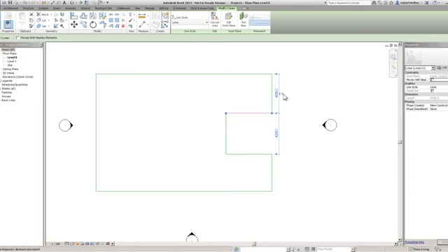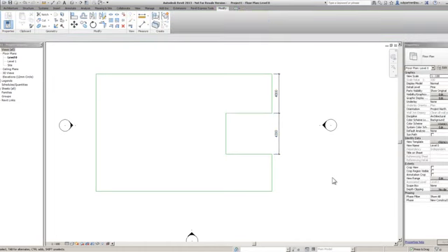Once we've done that, we're going to look at this. We have this little tool just here. If I hover over it, it tells you what it does, it says make this temporary dimension permanent. Let's click it and show you how it works. I'm just going to click off of it, so that I'm dropping anything I'm selecting. As you can see, the dimension is still there. It is now a permanent dimension. It's a proper dimension, as if we were drawing dimensions on our screen. If I hover over it, you can see how they're joined together. It's a running dimension.